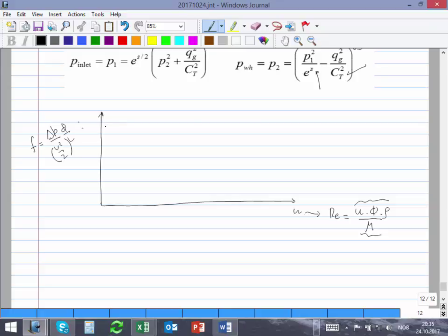Laminar. First you have one regime that you call laminar, right? And that's up to which Reynolds number? 2,300, okay? Maybe 2,500. Then you have some crazy thing that starts like a transitional zone, that we don't really know exactly what happens there. And then it starts going down again, and so this is the laminar, and here is the turbulent.